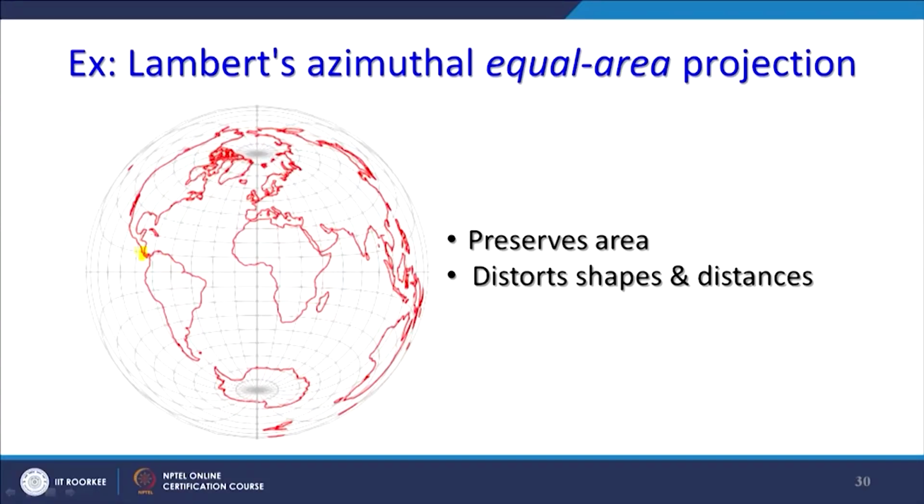But if I do distance measurement while projecting in this, say between here to India, I may get distortions in my distances. So, depending on the scale is also very much important. If I am working on a small area having large scale maps, then the curvature of the earth will not play much role, and therefore these things can be ignored. This is what the geographic projection.